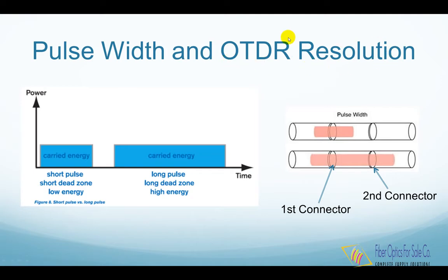The next thing you must understand is OTDR resolution. The OTDR test pulse has a length in the fiber, typically 5 to 500 meters long. It cannot see features in the cable plant closer together than that. If the light pulse is too long, the pulse will be going through both events simultaneously, and the OTDR cannot distinguish these two events, as shown in the picture. This has been a problem with LANs or any cable plants with patch cables, as they disappear into the OTDR resolution.